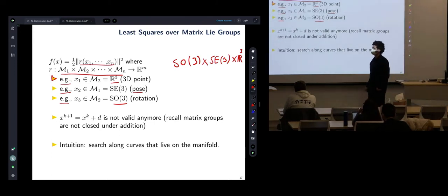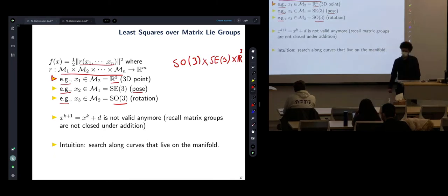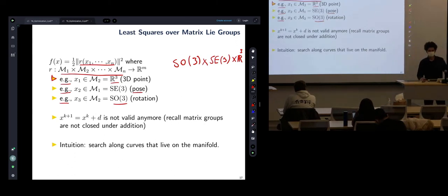Is this going to have different kinds of timestamp? Because maybe we're doing the filtering and also smoothing will have different kinds of timestamp, right? Yeah, the question is, will this have different timestamps? Yes. The optimization formulation is obviously agnostic of that, but in practice when we talk about robotics problems, data comes sequentially in time, and then the trajectory is a discretization of maybe poses at different time steps, and then maybe we want to estimate hundreds of them.